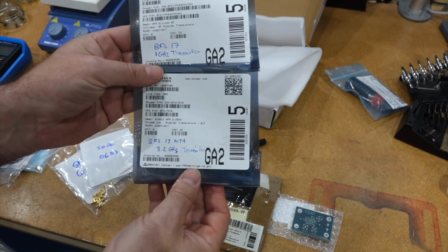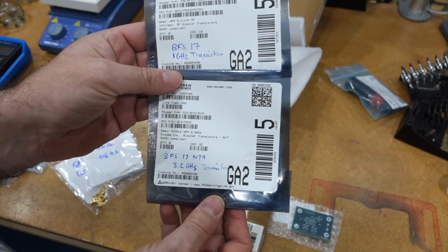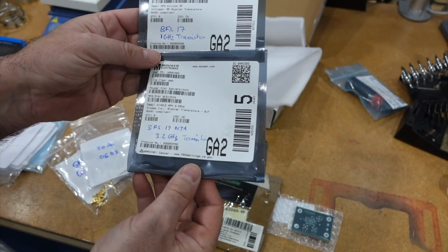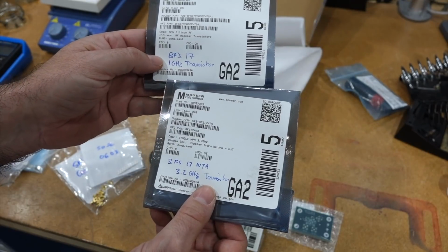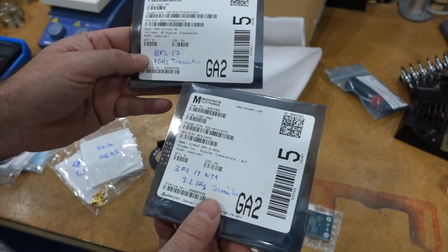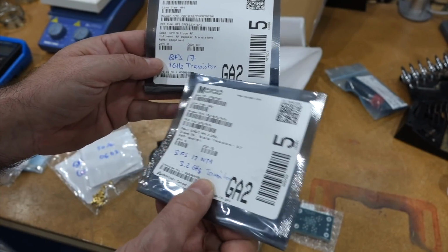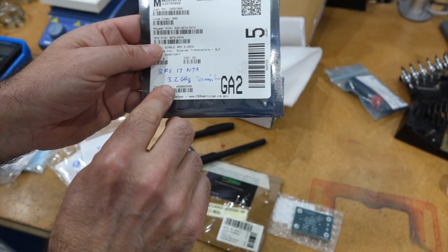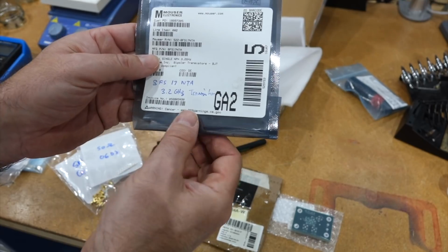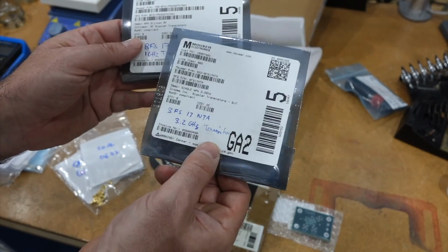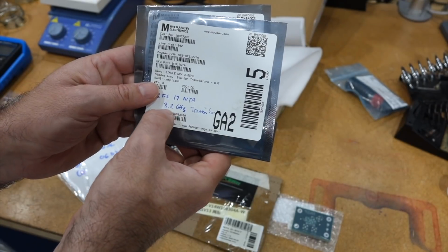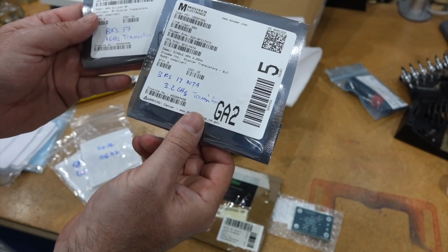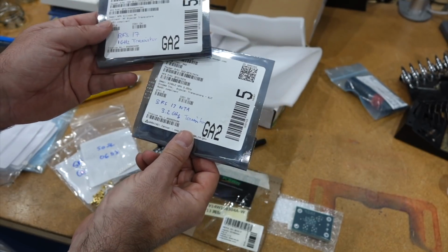Yes, and I got two versions of the BFS17. Unfortunately, I could not find the BFS17 that I had modeled with. So those are from other vendors, so they know it's BFS17, but it's not the same thing. One is a lower speed, 1 gigahertz kind of transition frequency, and another one is 3.2 gigahertz transition frequency, which might be a blessing or a curse. The curse is that they have a lot of gain at super high frequencies, so they can easily transform into oscillators. So we'll see which one will work.